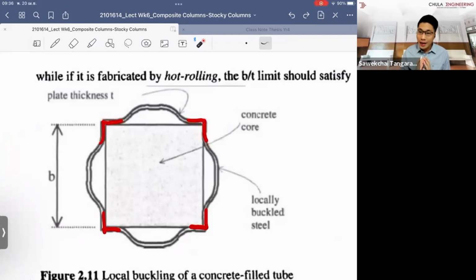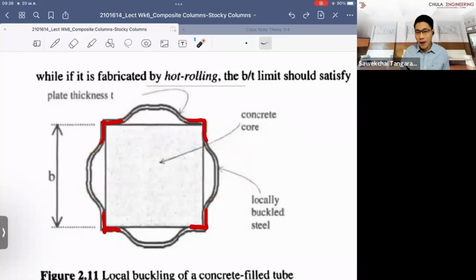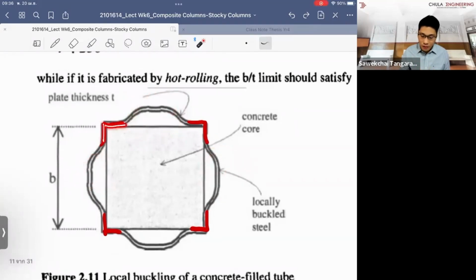So the area that hasn't lost its original shape, right? For this part, what you can see is from the buckling, and this one we call local buckling. When there is local buckling, in our calculation or in most of the standards, they treat this part as deleted. So they delete this part from the section and only leave what works as the effective area.